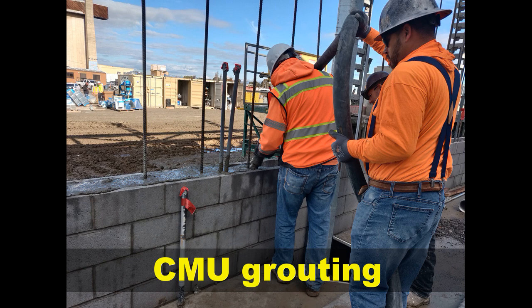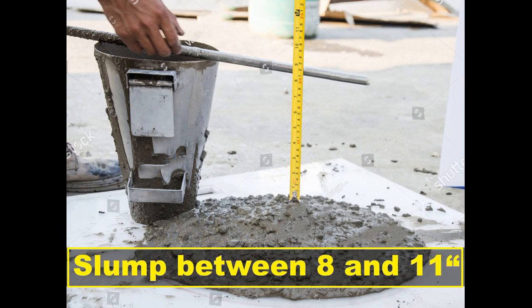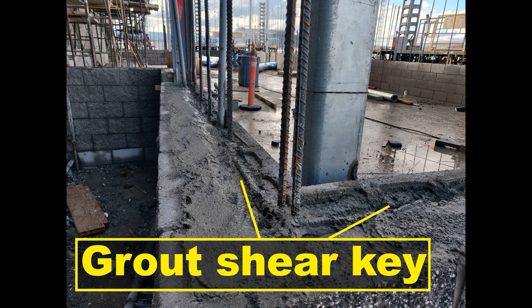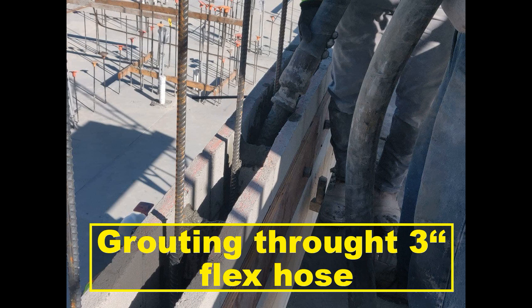Discard ready-mixed grout that does not meet the specified slump without adding water other than water that was added at the time of initial discharge. Allow sufficient time between grout lifts to preclude displacement or cracking of face shells of masonry units. Provide a grout shear key between lifts when grouting is delayed and the lower lift loses plasticity. If blowouts, flowouts, misalignment, or cracking of face shells should occur during construction, tear down the wall and rebuild.